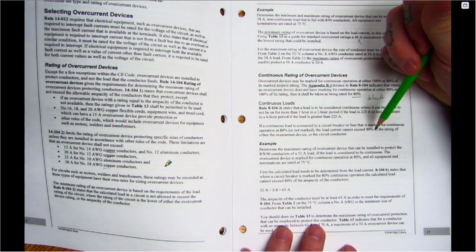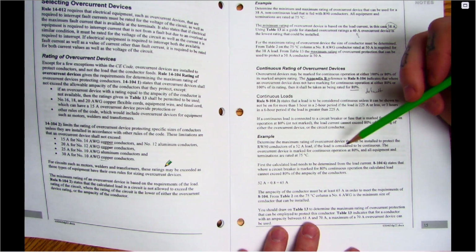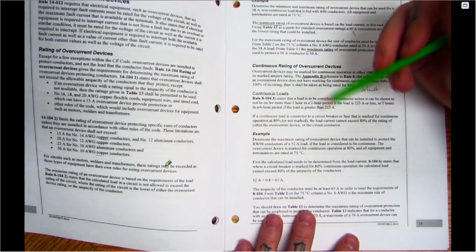Okay, so what we do is we upsize, again, inflate the ampacity before we choose a conductor. Kind of like a distance correction factor, or another type of correction factor based on heat or anything like that. Where again, it's not that the load's going to draw more, it's just we're going to do that before we pick the conductor.